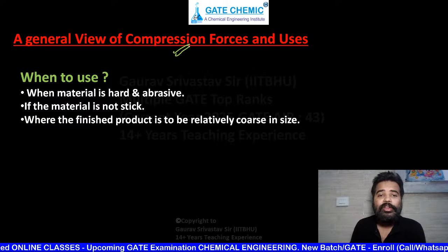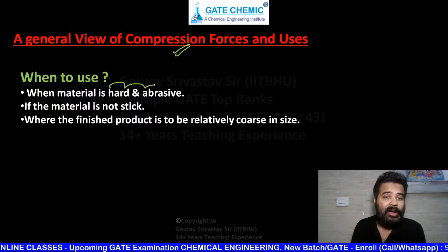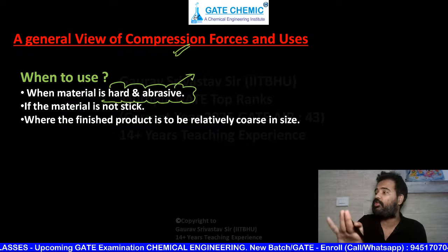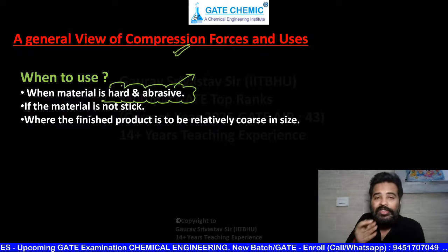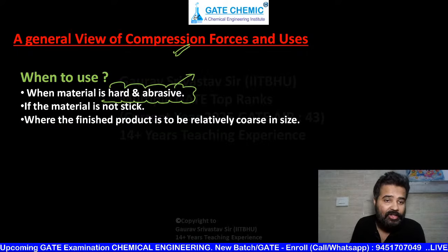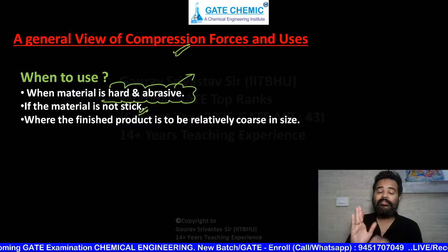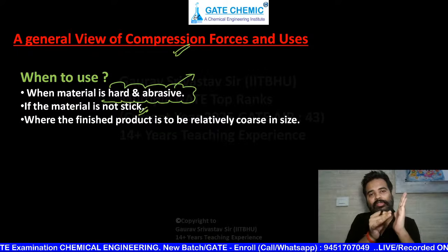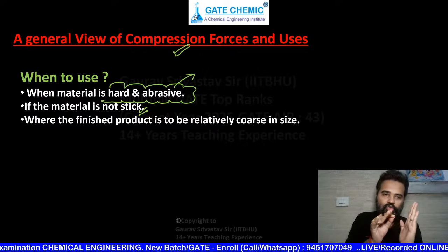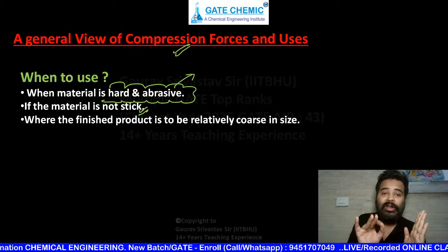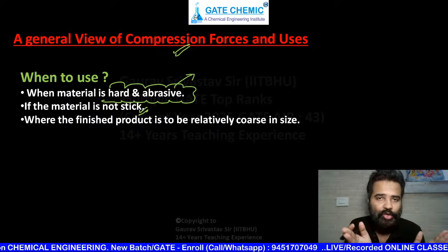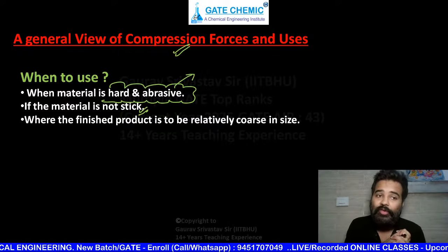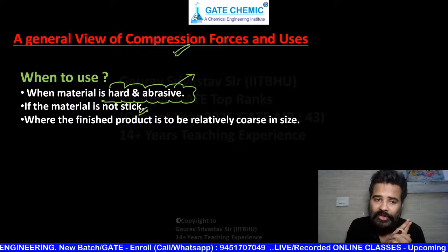Now, compression forces: you use compression forces when the material is hard and abrasive. Abrasive means it wears down another surface. Hard means resistance to scratch. The material should not be sticky; if it is sticky, then when you compress it for size reduction, the material will stick to the surface of the equipment. So if the material is sticky, you will not use compressive force to reduce its size. But if it is hard and abrasive, then you will use it. So when to use it: when the material is hard and abrasive, if the material is not sticky.